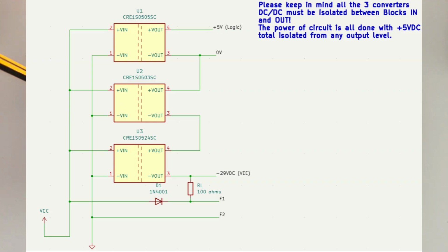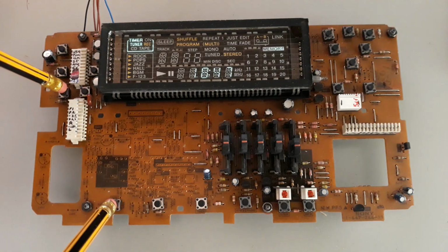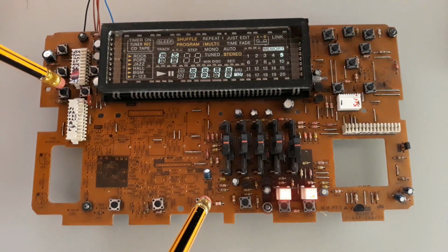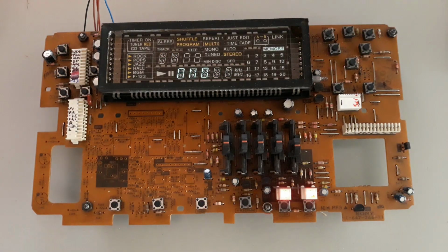This negative voltage was obtained by connecting two DC to DC converters in series, a B0505S and a B0524S. Once these three supplies are connected correctly, the panel operates exactly as intended. With relatively little effort, we can once again enjoy the display animations, clock functions, keyboard interaction, and even the audio-related features that made these systems so appealing when they were originally released.